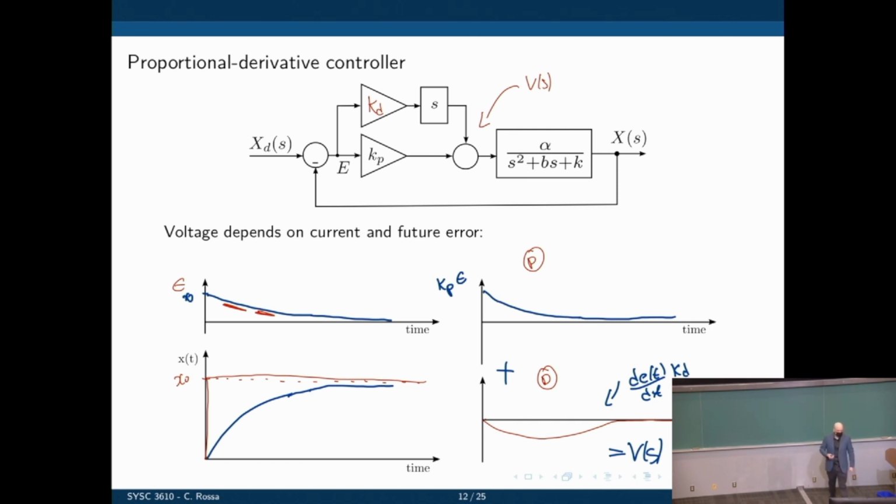If there is overshoot, notice that this reverses, because when there is overshoot, the error goes, let's say, positive and negative. When it oscillates, when it starts to increase again past the overshoot, let's assume that this was an underdamped system. If it was an underdamped system, it would oscillate, something like that. So the error would oscillate as well, right? Because at some point we went beyond what we wanted. Now the error is positive, now the error is negative.